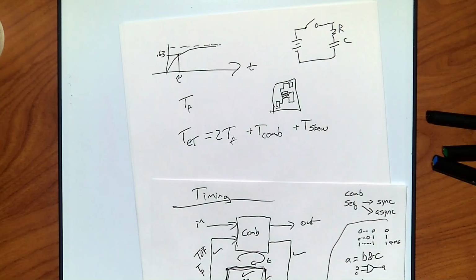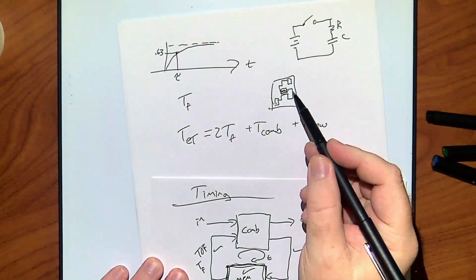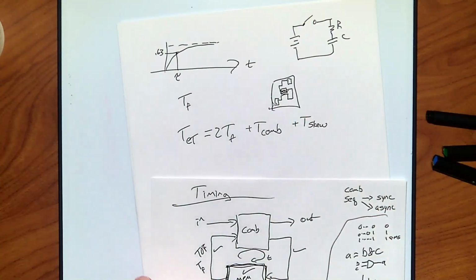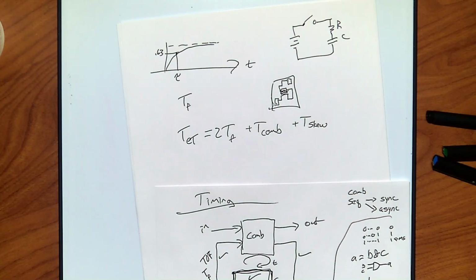This is why clocks have their own network layer inside an FPGA. This is why you cannot build a logic circuit to act as a clock, because normal things have to be routed in this stupid way. If we make a clock layer, I can make it really fast and it just goes the shortest time. Right? There's no problem moving, it just gets there as fast as I possibly can.